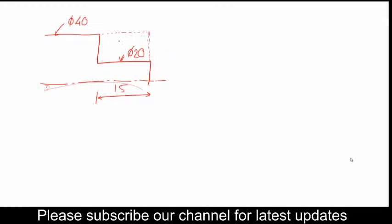We have to remove this part. We have to remove this rectangle. Okay, and for this, let us take CNMG. CNMG means it must have an angle of 80 degrees, and it is of rhombus shape. If we see it totally, it would be of this shape.